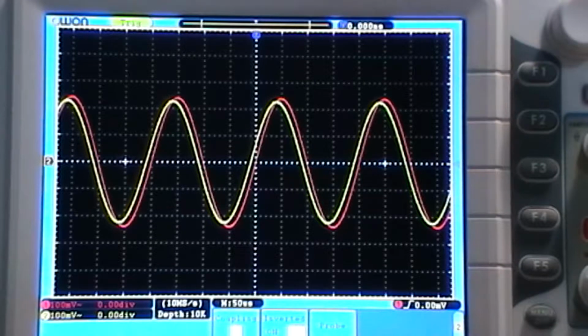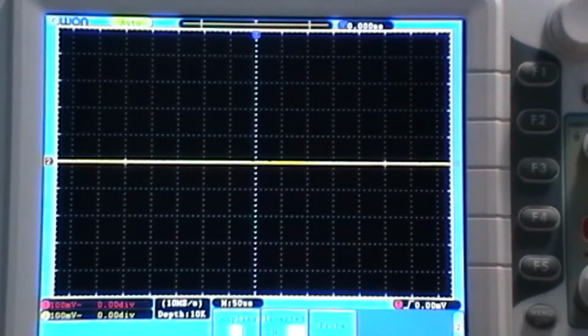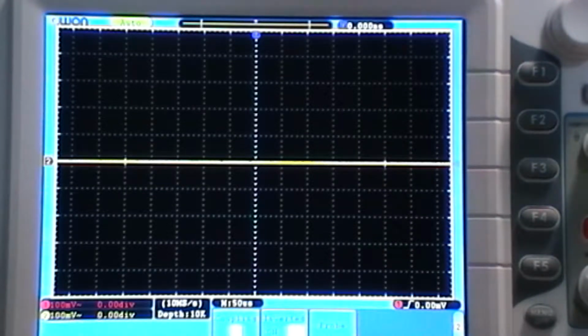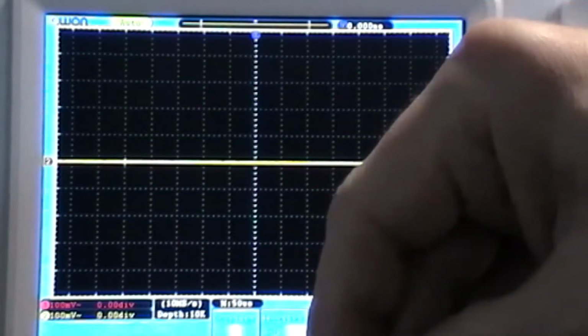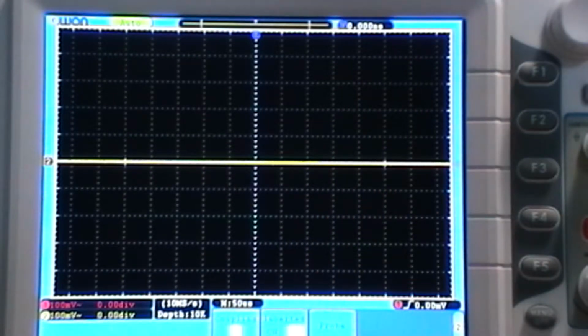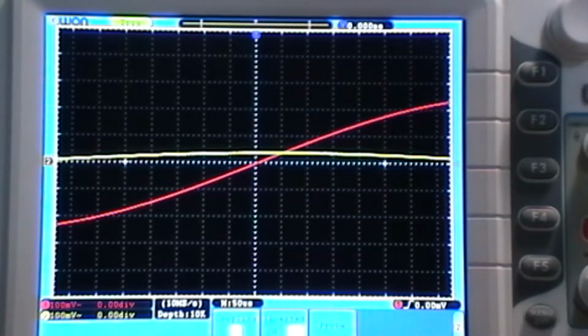So let's turn that off and change the capacitor now to a 47 nanofarad. So 47, yeah, there we go. Plug that in there. Turn on the frequency. I'm going to leave it at 5 kilohertz this time, and we'll see what it's like now. Perhaps I should change it and put it back to 500 Hertz, which is where we've been starting all the time. So we will start at the same point. 500 Hertz, half a volt.